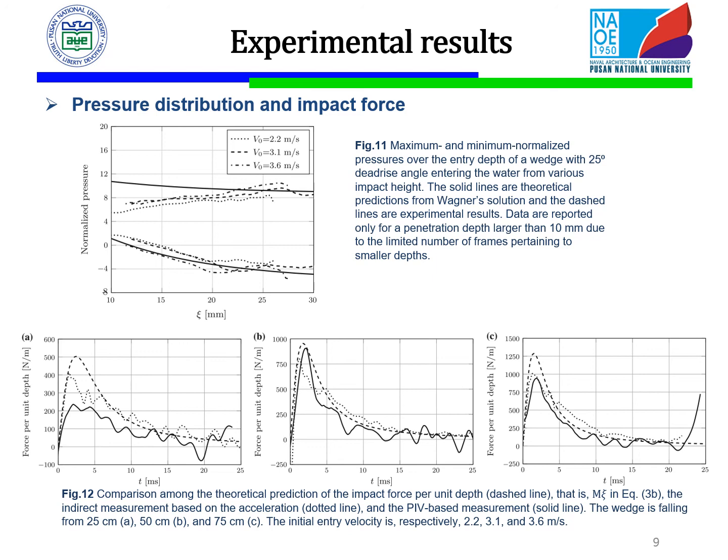Figure 12 confirms the accuracy of the PIV-based indirect force measurements in water entry problems. PIV-based measurements are found to be in close agreement with both theoretical results from Wagner's solution and the experimental findings based on the measurement of the wedge accelerations.